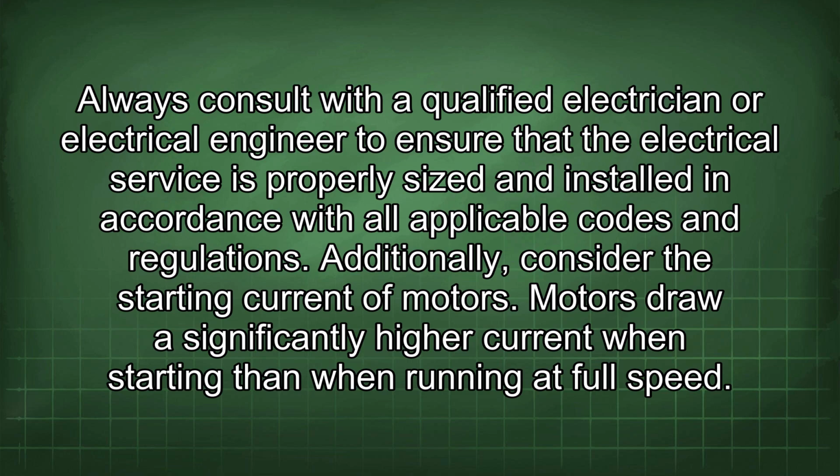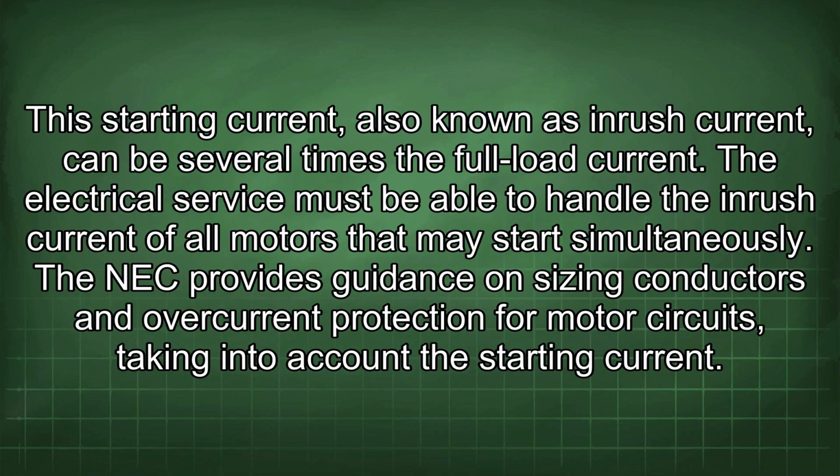Additionally, consider the starting current of motors. Motors draw significantly higher current when starting than when running at full speed. This starting current, also known as inrush current, can be several times the full load current. The electrical service must be able to handle the inrush current of all motors that may start simultaneously. The NEC provides guidance on sizing conductors and overcurrent protection for motor circuits, taking into account the starting current.